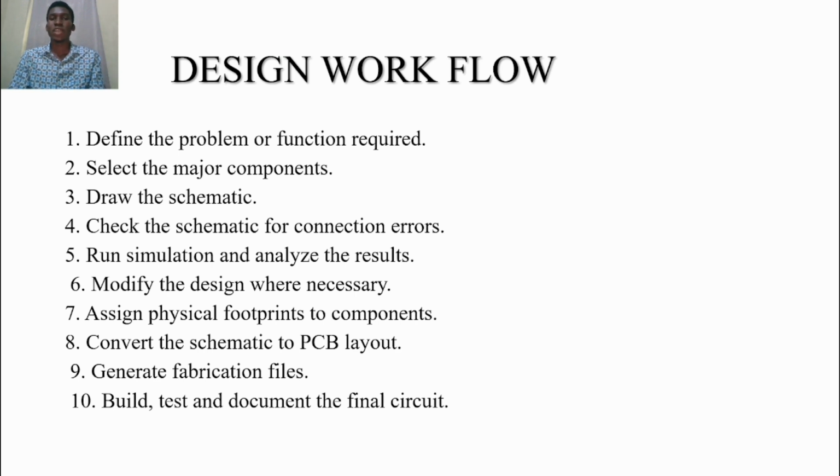We first have to define a problem, select the major components, draw the schematic. We check the schematic for correction errors, that's the electrical rule check. We run and simulate the results. We modify the design where necessary, design the physical footprint of the component, convert the schematic to PCB layout, generate fabrication files, then finally build and document the final results.